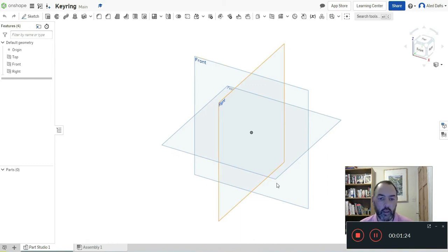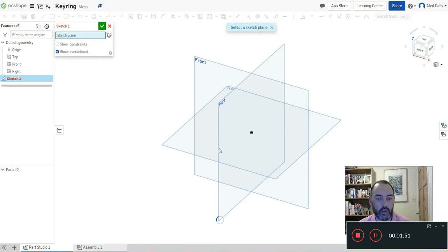So in the design screen on Onshape, it gives us 3 work planes, okay, front, top, right. It doesn't really matter which one you pick to start off with, and you can imagine these to be something like a sheet of paper which we start sketching on. And that's exactly what I'm going to do. I'm going to start sketching by clicking on the sketch tool, and I'm going to select any of these planes, and it doesn't really matter which plane I pick. I'm going to pick right,